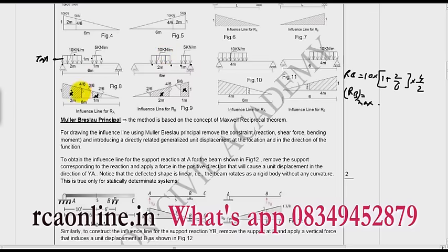So let us do it. What is the value of RA now? RA will be 10 multiplied by 1 plus 4 by 6 into 2 by 2, plus 5 into 3 by 6 plus 2 by 6 into 1 by 2. This is the value of RA. If you solve it, what will you get? You will get RA as 18.75 kilonewton.